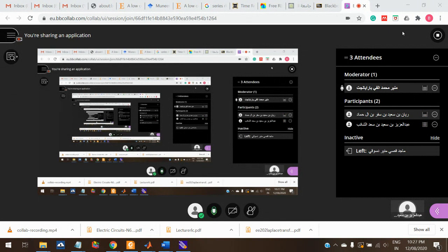You understood? But another case is there, the first case I told you, real and imaginary. If there is a real number and an imaginary number, the roots will both have the same real part, minus alpha, but the imaginary part will be j omega naught and minus j omega naught. This will be the case. So you have omega naught, so there will be oscillation. Am I correct?